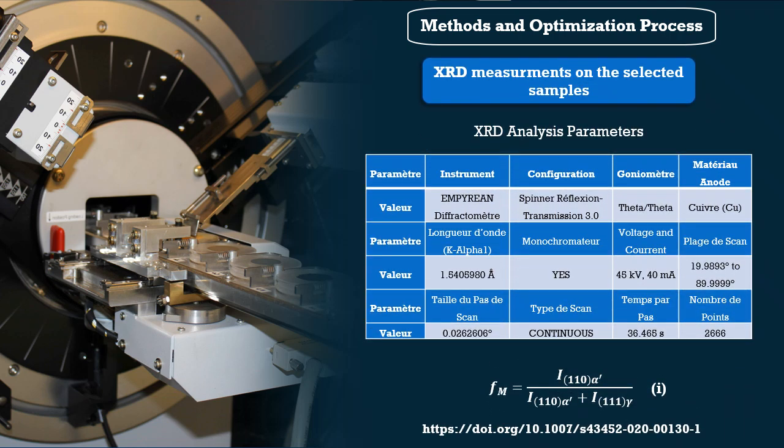Samples were then prepared from the deformed specimens to be analyzed using XRD to get the phase composition variation. The analysis was performed using the parameters listed in the table here, and the equation shown here is used to calculate the martensite volume fraction based on the intensities corresponding to the alpha prime martensite and the intensity of the austenite plane.